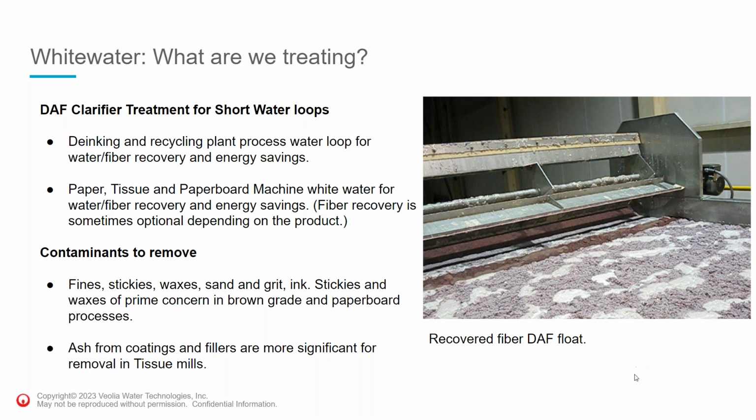If we're on a paper machine or paperboard machine whitewater loop, we want to clean up the water so we can reuse the water to some extent in showers and for dilution. At the same time, in addition to saving water and recovering water, we can sometimes recover the fiber depending on the quality of product that we're making.